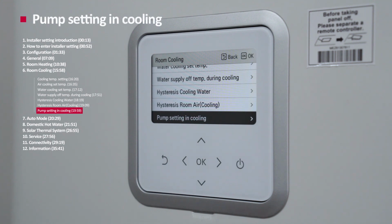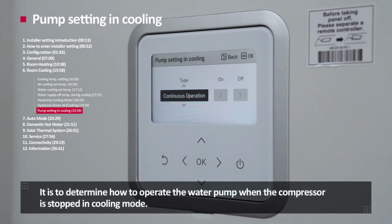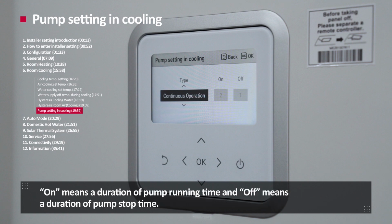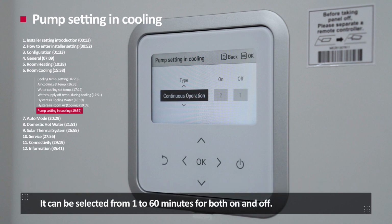Pump setting and cooling. It is to determine how to operate the water pump when the compressor is stopped in cooling mode. By using type, you can choose whether to operate the water pump continuously or at a certain interval period when the compressor is stopped. On means the duration of pump running time, and off means a duration of pump stop time. It can be selected from 1 to 60 minutes for both on and off.